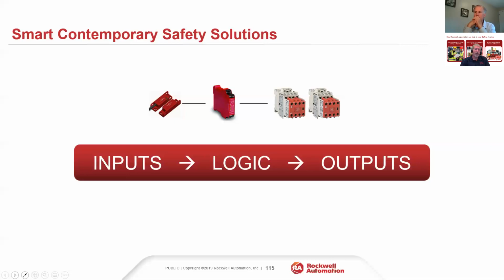However, we never know if that switch is going to actually work until we put the requirement on it, right? Because it is a dry set of contacts. We cannot determine whether that set of contacts is somehow damaged and in a fixed position that will not move, whether that's a welded contact, whether that's a physically damaged switch. We can't tell. We will never be able to tell that. That is a fault we cannot detect. We eliminate that fault with the OSSD devices.